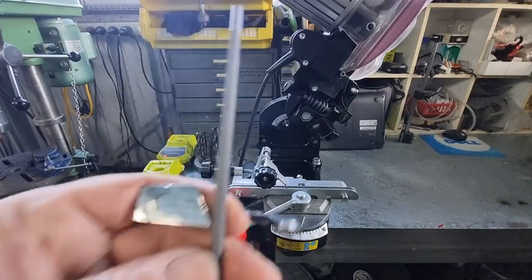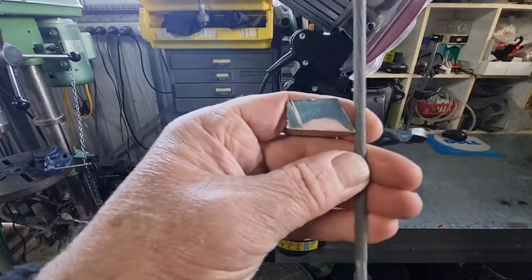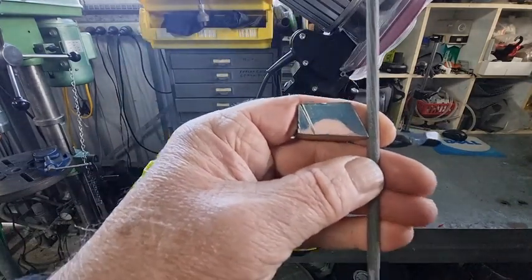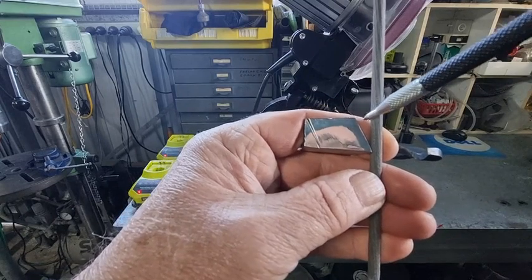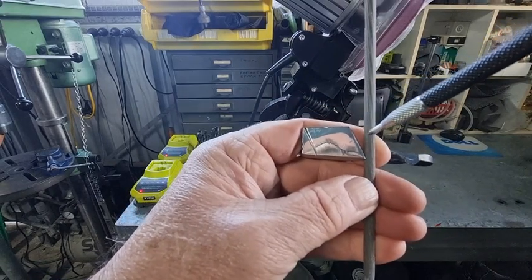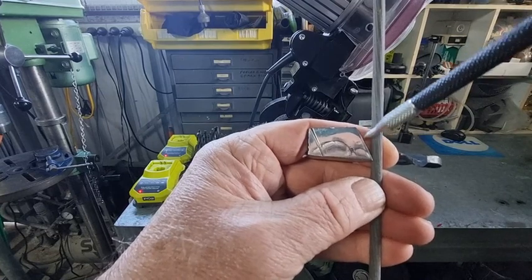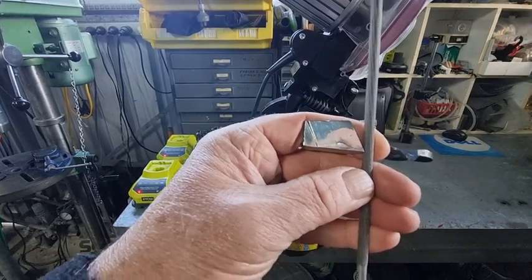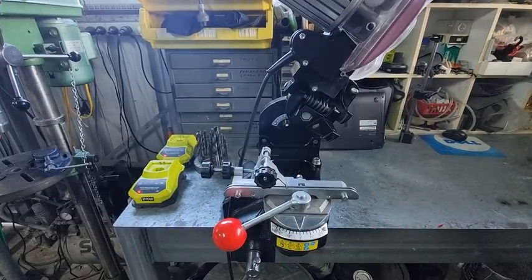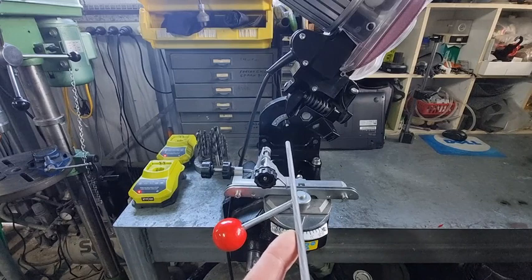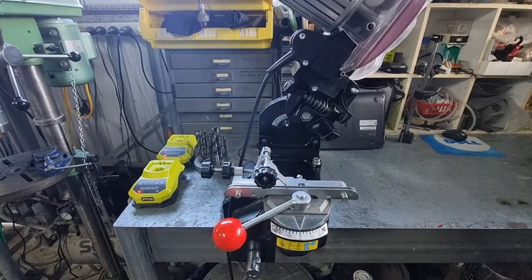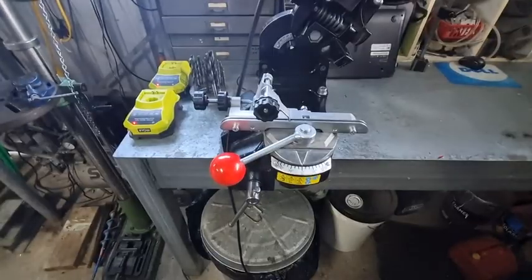Yeah, that'll work. Okay, so when we talked about the 30-degree file angle, we're talking about this angle that's in between here, between the file and the face, this face here. That's 30 degrees. So it's referred to as a filing angle. And as I said, it comes back from the day where you'd hold the file perpendicular to the chainsaw bar and you would move 30 degrees. So that's where that comes from, and that's fine. That's pretty easy to understand.